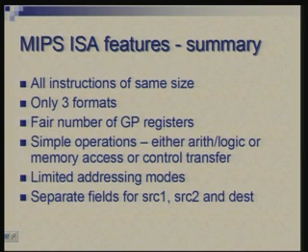There are limited addressing modes. Okay. So, with each instruction there is a fixed addressing mode, and each mode is applicable to specific instructions, and there is no orthogonality. Along with a wide number of registers, we have provision for specifying 3 fields in many of the instructions which perform arithmetic or logical operations. So, source 1, source 2, the 2 sources can be specified independently, and so can be the destination.